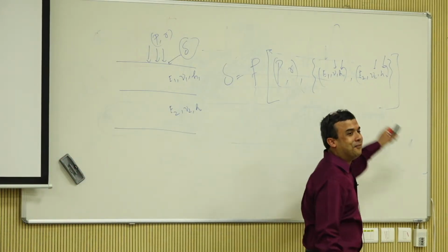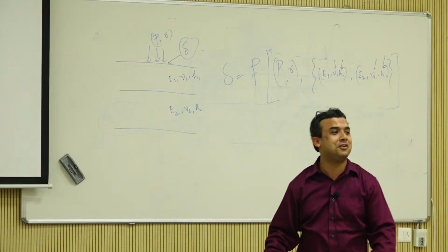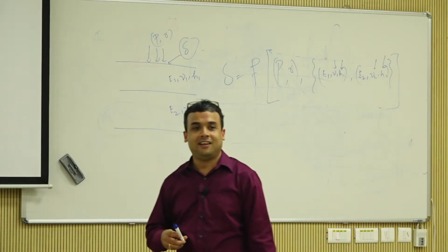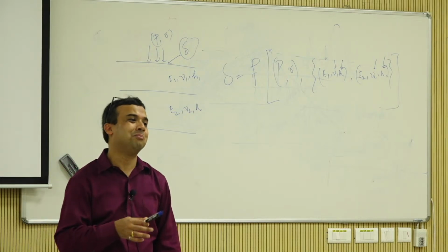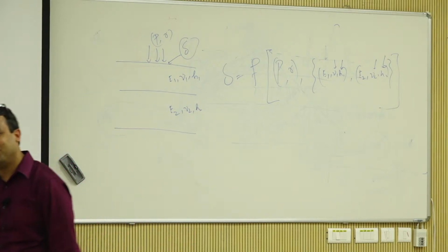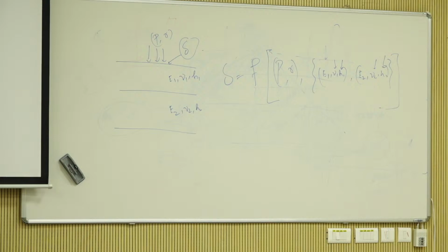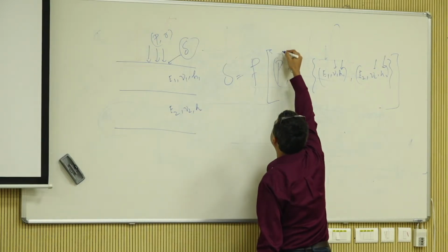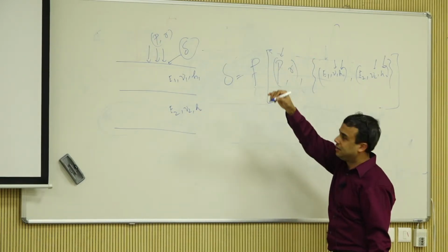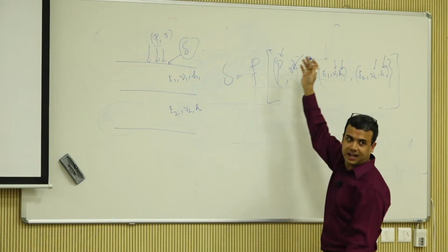So what is the Poisson's ratio for concrete? No, 0.35 is too high. That's asphalt. 0.15 for concrete; 0.3 to 0.35 is close to asphalt. Aggregate is about 0.3, 0.35. Subgrade soil, you usually take 0.4, something like that. So what I'm saying is Poisson's ratio is not very sensitive. You probably know this. Do you know P? Do you know R? Right? So what do you not know?